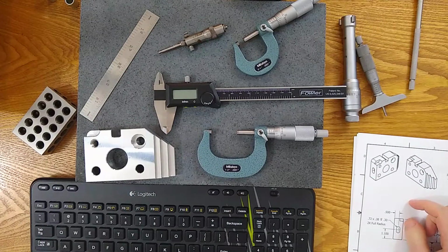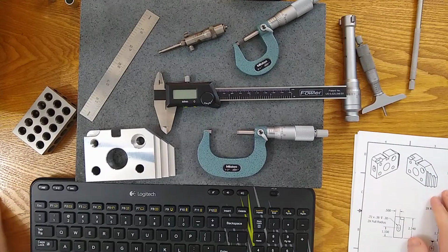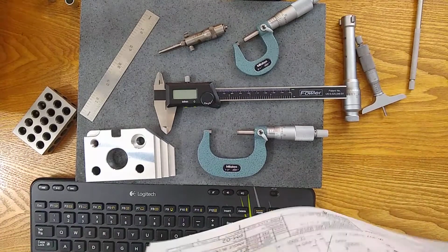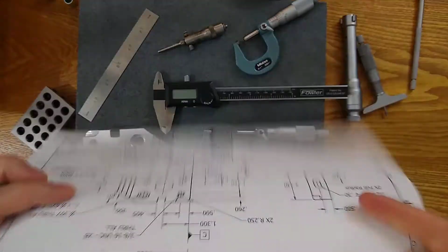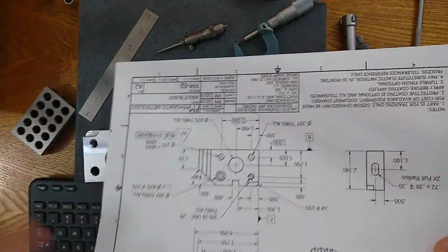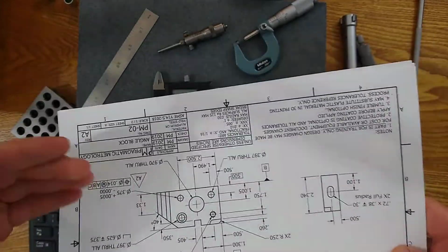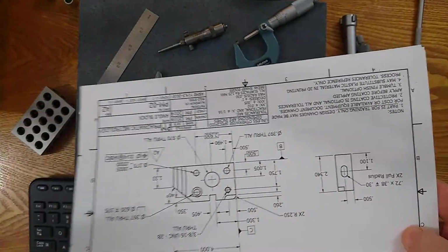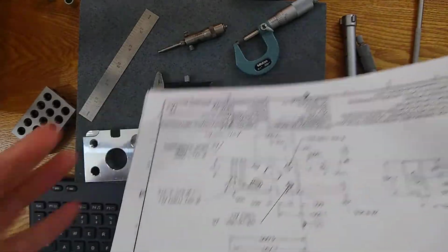Okay, so I look at some steps to decide, and number one, first thing, and the reason it's first, most important, look at your print requirements. I always say, grab the print, take a look at your tolerance zone, take a look at the whole part itself, the way the datums are laid out, the way the implied datums are, tolerances, and come up with a game plan for how you're going to do each feature, how you're going to do the part as a whole.